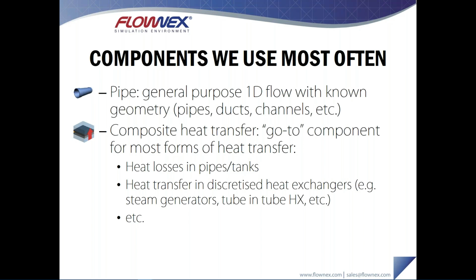The nice thing about it is that it will automatically match the discretization of the pipe component that it's connected to. So with the other heat transfer components, you'd have to drag and drop components and build your discretization manually. The composite heat transfer automatically follows the discretization of the pipe. So in terms of time spent dragging and dropping, this component really saves you a lot of effort there.